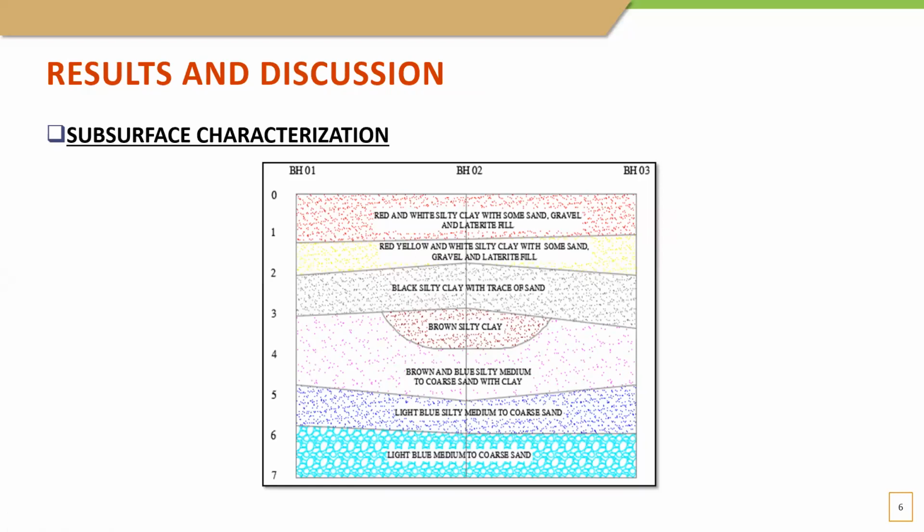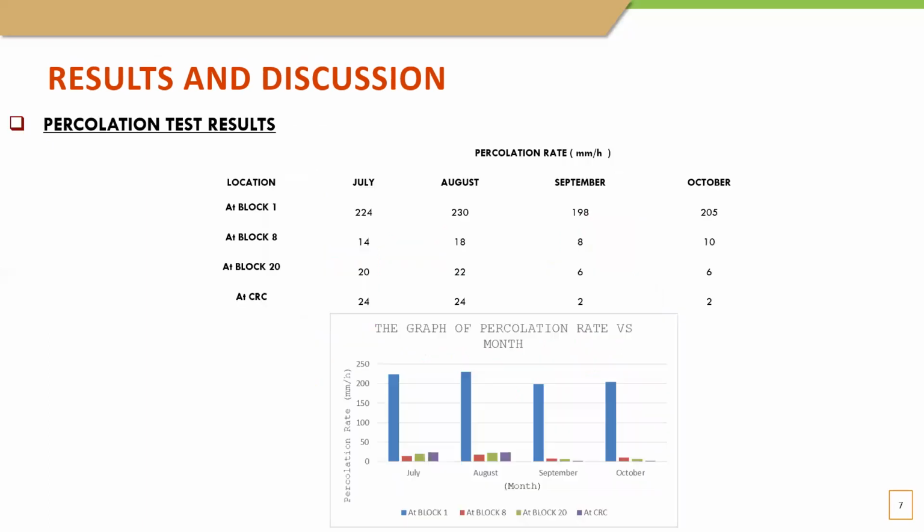You can see that we used a borehole location and borehole log to identify the soil profile. It is taken from the auger hole, and we used about 2.5 meters for our project description. So you can see that there is sandy soil and clay with sandy soil in this layer.